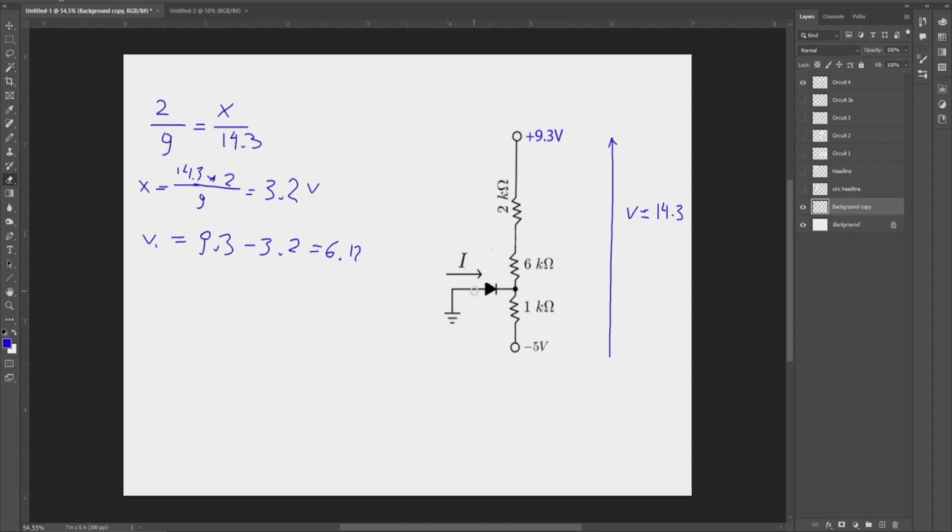Now, is this diode conducting? Because the question is what the current is here. Well, if the diode conducts, we're going to have some value. If this diode is forward biased, which means this voltage has to be greater than that voltage. So we know what this one is sitting at. This is sitting at 0. So this has to be at least minus 0.7 volts if this diode is conducting. So let's just pretend that we don't have that diode here, and let's see what the voltage is at this point.